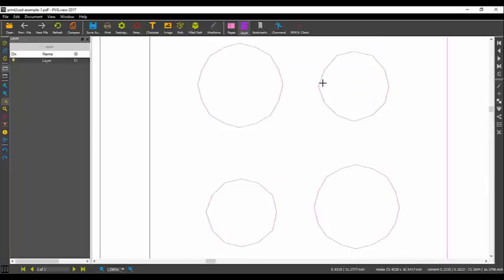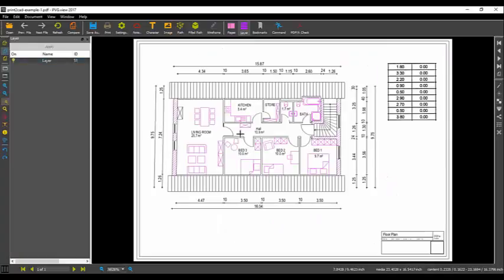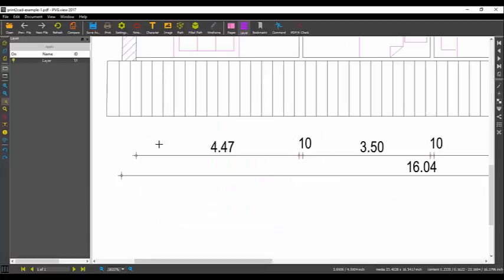And now, only one thing you have to know. If the CAD program is not able to produce well-done circles here, the other coordinates will be terrible too. Now, if you try, for example, to measure this 447 and this 350, you will receive something with a terrible accuracy.